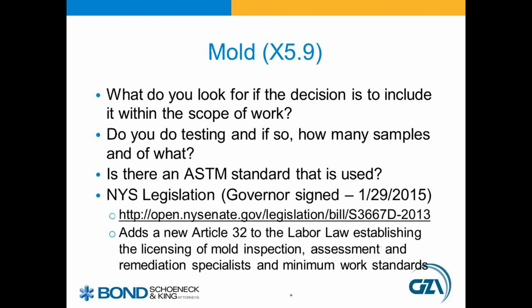One of the more recent concerns that has developed as a result of the large storms we've experienced over the past decade, such as Katrina and Hurricane Sandy, is mold. When you're concerned about mold, you want to look to see if there are any wet areas or mold-like staining in your property. If your building is right next to a wetland, it would be advisable to sample for mold. If there's prior water damage from a fire, or storms, or flooding, it could be very likely there's mold in your building, which again can be costly to remediate.